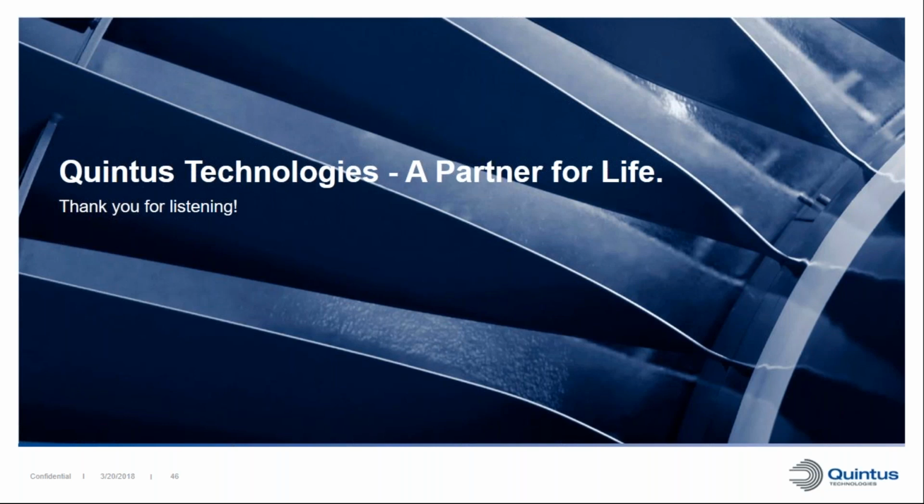Another question is from Aiden. During the LMD process, it is possible to have retained austenite due to build-up. Do you think that it is possible to decrease the retained austenite by high-pressure heat treatment? Might be. I don't really know how to answer that question. It depends on why we get the retained austenite. But we can get very high cooling rates in the HIP. We can cool down to room temperature, so pretty much similar to any other quenching method, to try to get martensite or whatever we want.